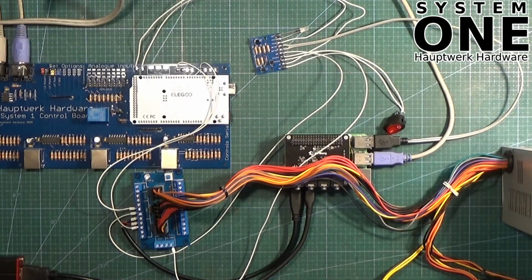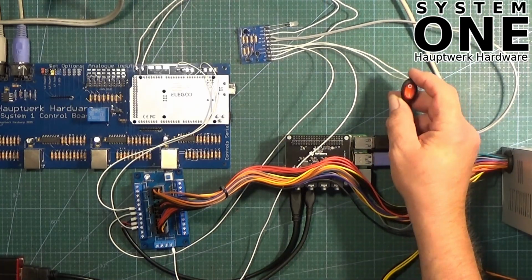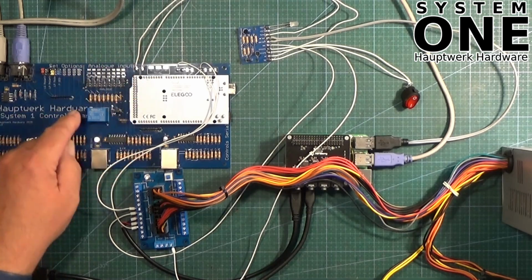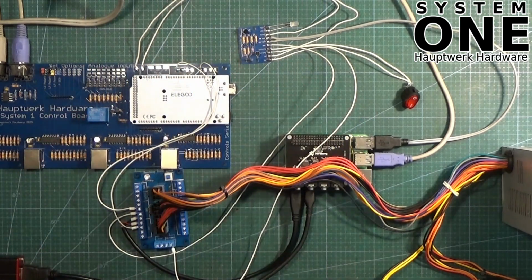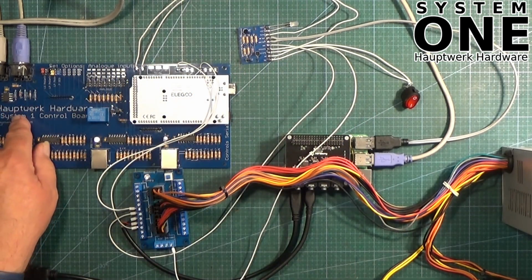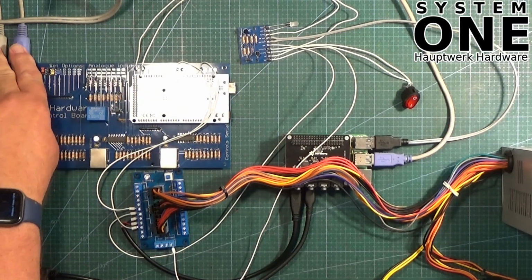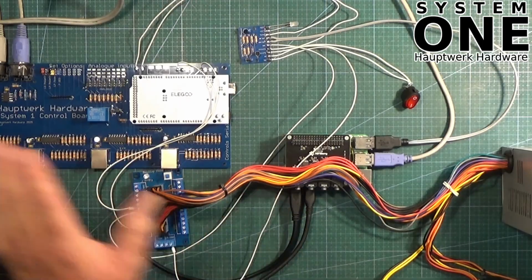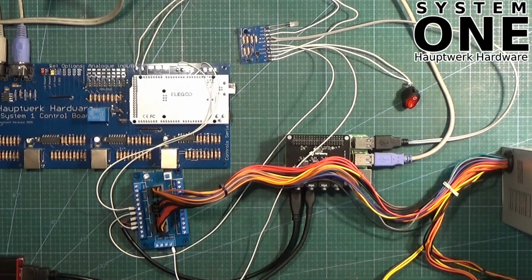And then when it's time to shut down, and we switch this switch off, again, the switch state pin here will see that change of state with the switch, and it will cause the control board to send a MIDI signal via our Turtle Beach MIDI interface, which will go back to the Pi or Hauptwerk or whatever you're using, and then that will be set up to initiate a save for Hauptwerk or JOrgan or whatever you're using, followed by a computer shutdown.